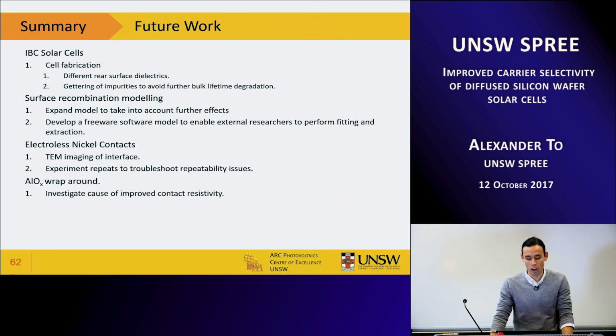Sorry, that's a repeat. Future work: we're still working on the IBC solar cells, that's ongoing, and we're working on the baseline process, and we're going to try this experiment with different rear dielectrics. If I can find the time, I'll try and write up that surface recombination model into freeware software that people can use to simulate and fit lifetime curves. And with the electrolytic nickel plating, we're still doing some characterization to try and understand what's going on. With the ALOX wraparound, it would be really good if we could investigate the cause of this improved contact resistivity, as opposed to simply reporting what the effect is.